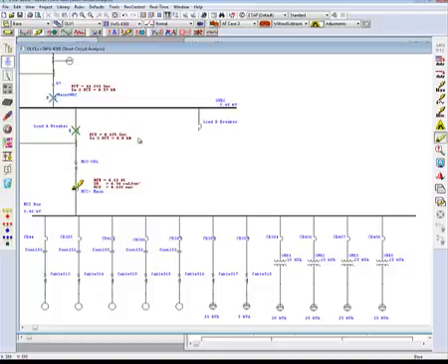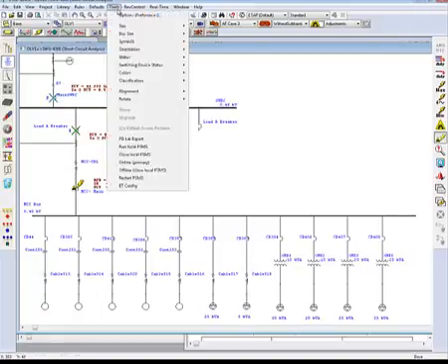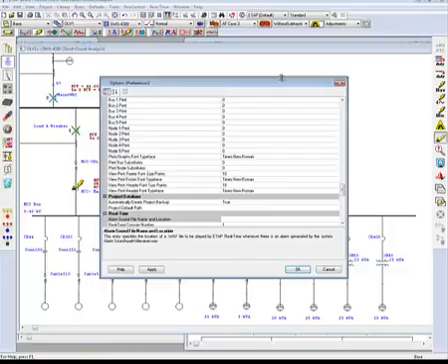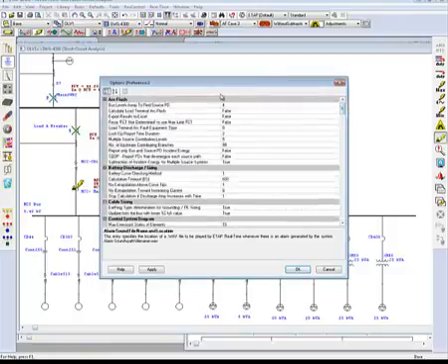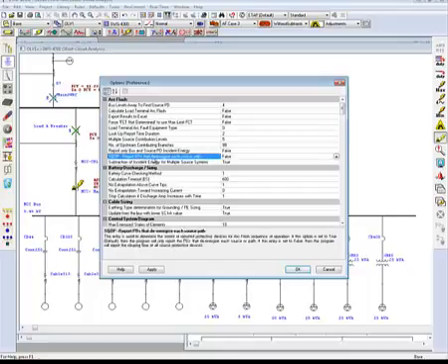There is another setting for the arc flash sequence of operation, which is the modes of operation, or the amount of flashing during a sequence. This setting is enabled through the Tools Options preference. Under the arc flash section, there is an option titled Sequence of Op, Report PDs that de-energize each source path.